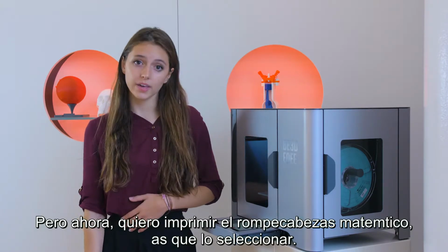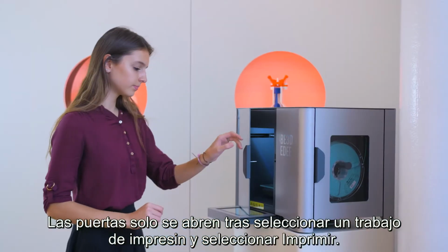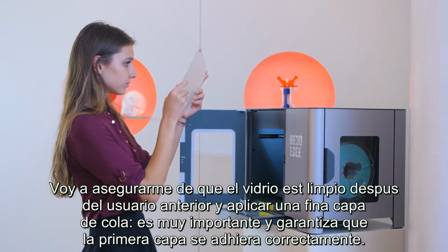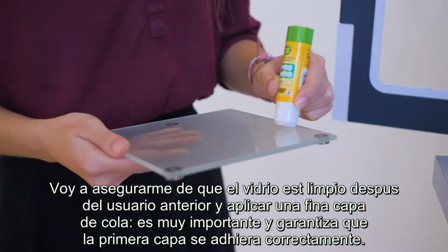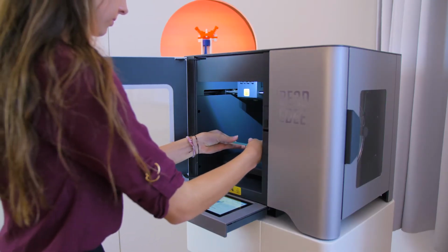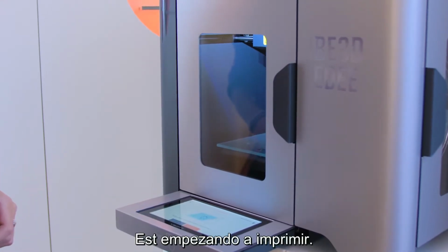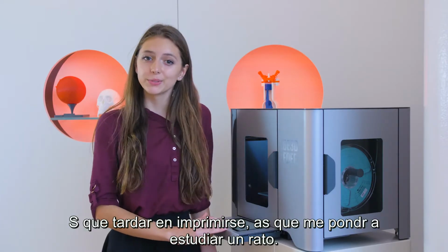But now I want to print the math spinner, so I'll choose that. The doors open only after I have selected a print job and select Print. I'm going to make sure that the glass is clean after the previous user and apply a light layer of glue. That is very important and ensures the first layer adheres properly. Okay, we are ready, so I'll press Start Printing. It's starting to print. I know it'll take a while to print, so I'll go do some studying.